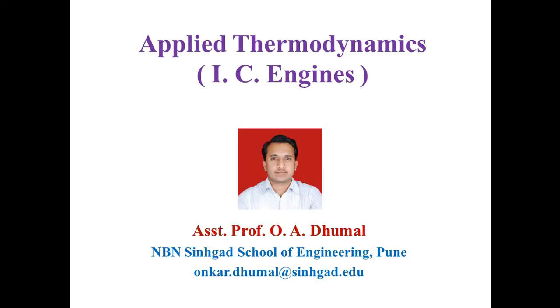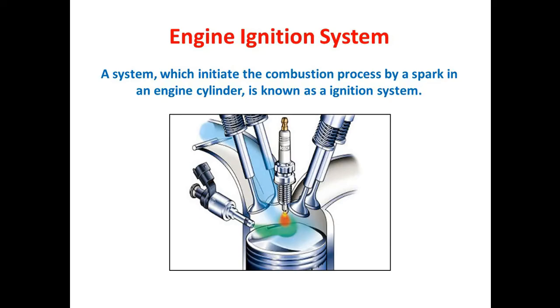Hello everyone. Today in this third session we will discuss the engine ignition system. A system which initiates the combustion process by a spark in an engine cylinder is known as the engine ignition system. In SI engines, to initiate the combustion process, an ignition system is required. Also, in SI engines, we know that the compression ratio is quite low, and the self-ignition temperature of the fuel is high, so the ignition system plays a quite important role in the combustion process.